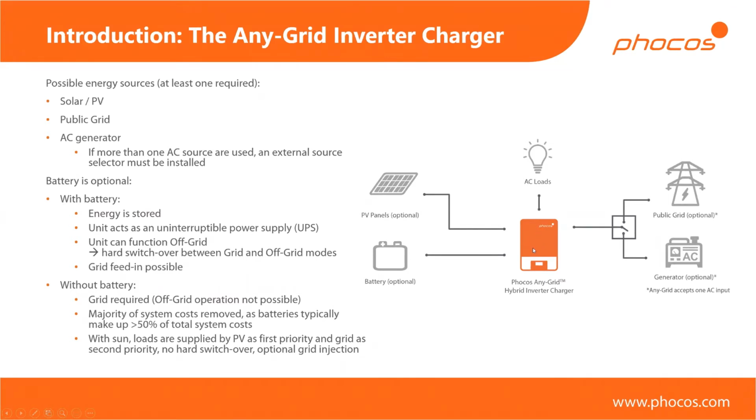Now the inverter, for example, would keep running, would maybe discharge the battery at night, for example, because there's no PV coming in. And then at some point you can use the relay on the inverter itself to turn on the genset when you really need that power. But you've already done the switching beforehand simply because of your logic up here.